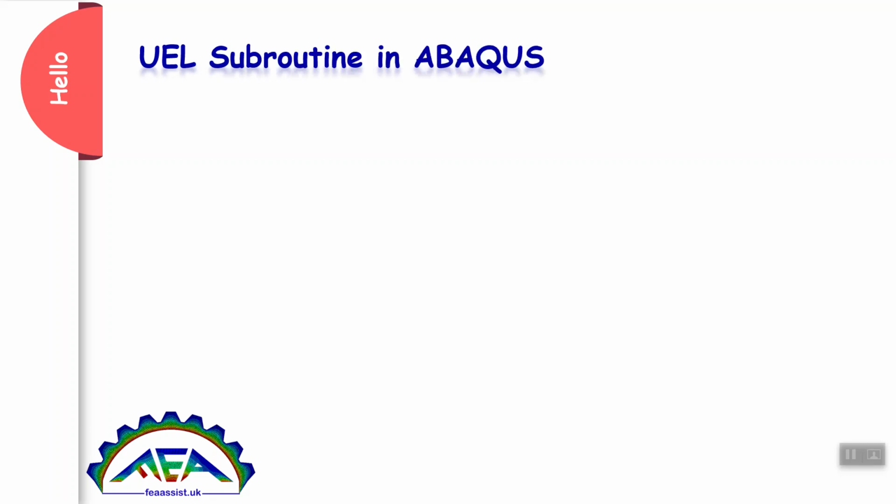Hello? You want to learn UEL subroutine in Abaqus easily and quickly. UEL is a subroutine to define a new element in Abaqus. Consider you have a one-dimensional element with points A and B. For example, temperature in this element is interpolating between the temperature of point A and temperature of point B. So, an interpolation function computes and defines the temperature at any point in this element.